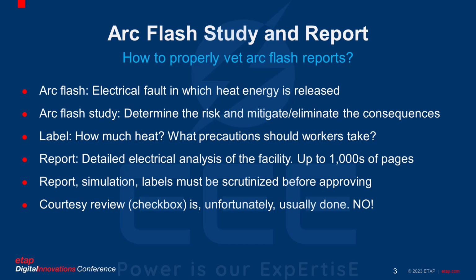What is an Arc Flash study? We have this safety incident called arc flash. When an arc flash occurs, there is a release of heat that could fatally burn the worker. An arc flash study examines the entire electrical facilities and determines the risk of an arc flash incident. A report is written and it provides steps to eliminate and/or mitigate the consequences.